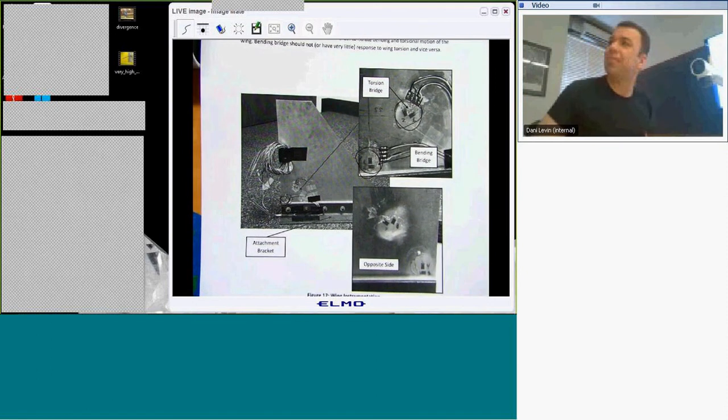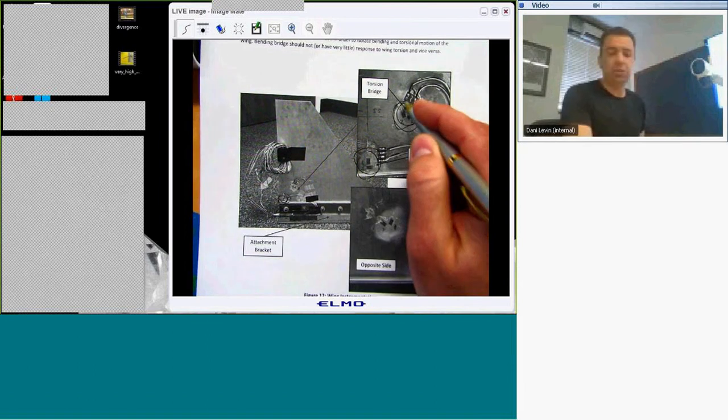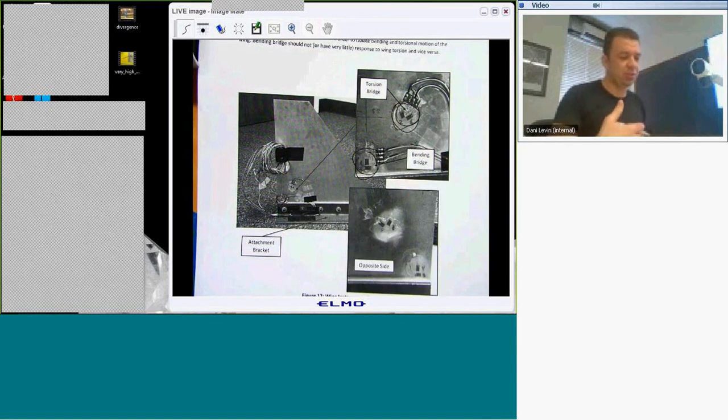Is it related to redundancy also? No, it's not redundancy. I wanted to amplify the signal. With the full bridge, the signal is amplified by 4. You need this because the readings of the bridge are in millivolts, and you need to accommodate all of your hardware capabilities, so you want to amplify the signal.